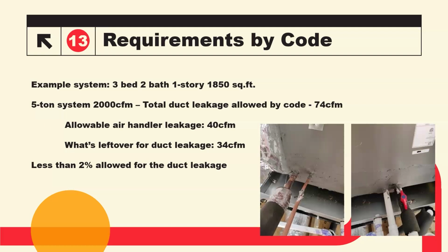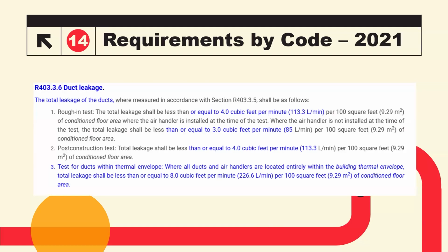So as I said earlier, most HVAC contractors will do their due diligence. They'll actually seal all these things up. Manufacturers send out seals and grommets for the intentional openings of the unit, but a lot of times these things are tossed out in the trash. They're not properly installed. And so what you see here in this picture is them just going the extra mile and just adding mastic to that stuff just to get it sealed up like it should be.